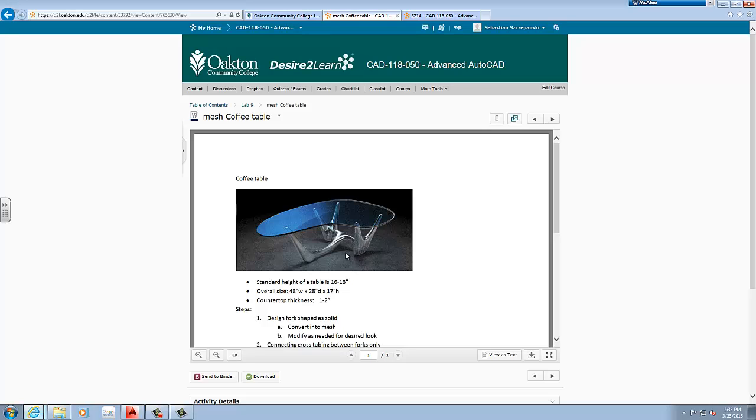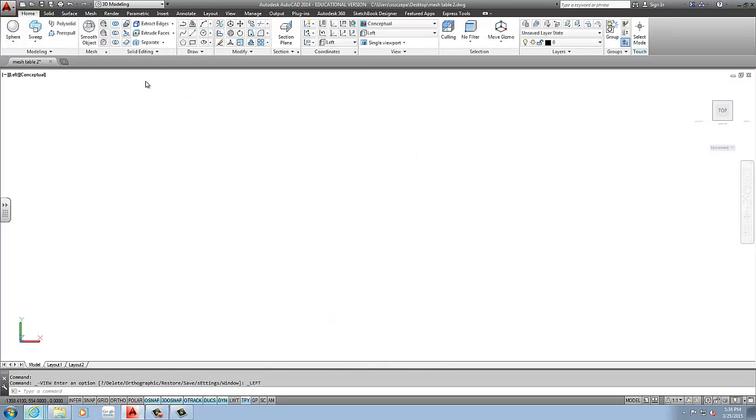I'm going to create a rectangle, as you can see, a little rotated, and this is a mesh. The way I can verify it's a mesh is by selecting the whole object. If you go to the Home tab up here, you will see a Create Mesh portion and a Smooth and Convert Mesh portion. That pretty much tells you that this is a mesh object.